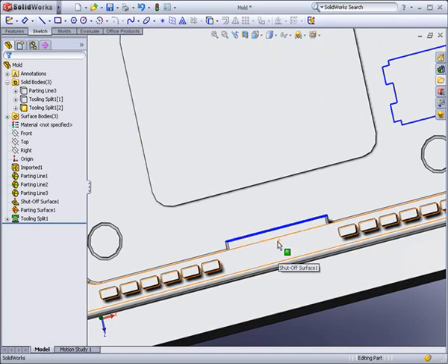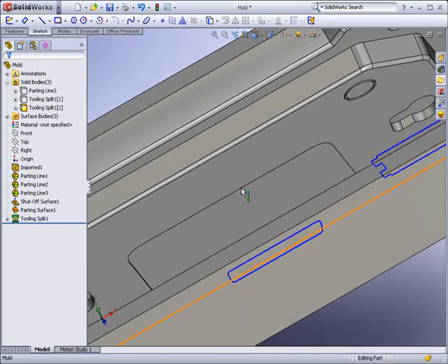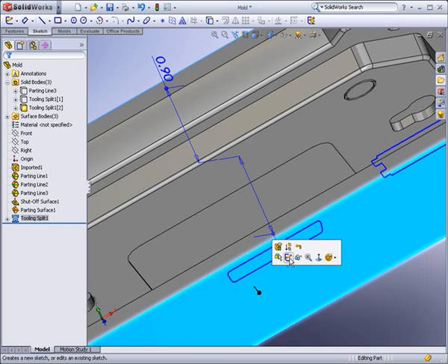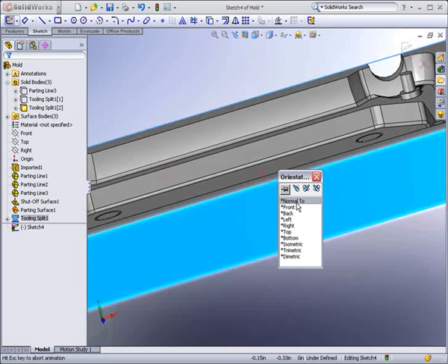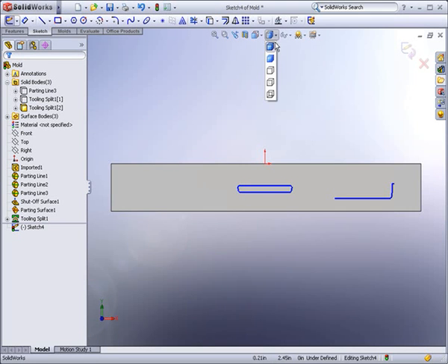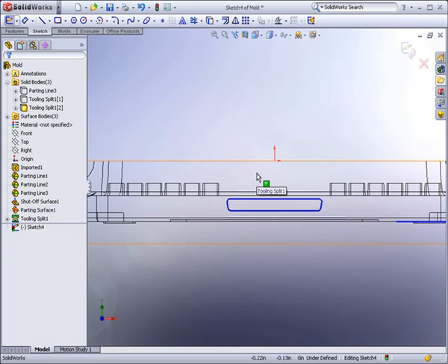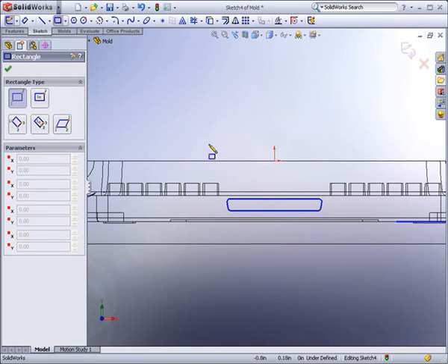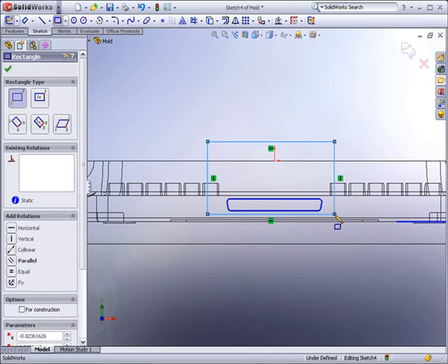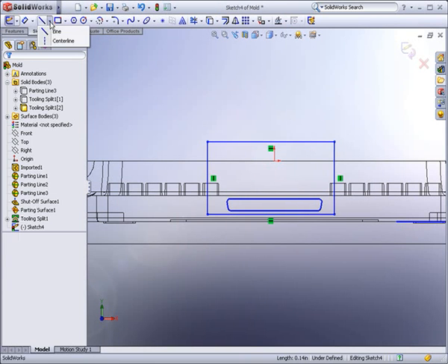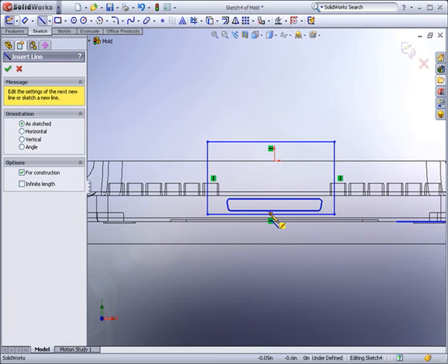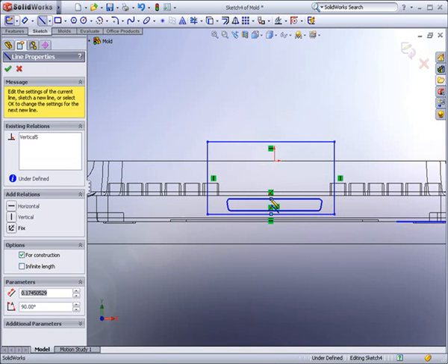On this side of the part, we find an undercut. We'll need to make a side core. By switching to a wireframe display, you can quickly sketch geometry in order to capture and extract the side core from your design. Because everything is sketch-based in SolidWorks, you can easily and quickly create relationships to center the geometry on the side core extraction.